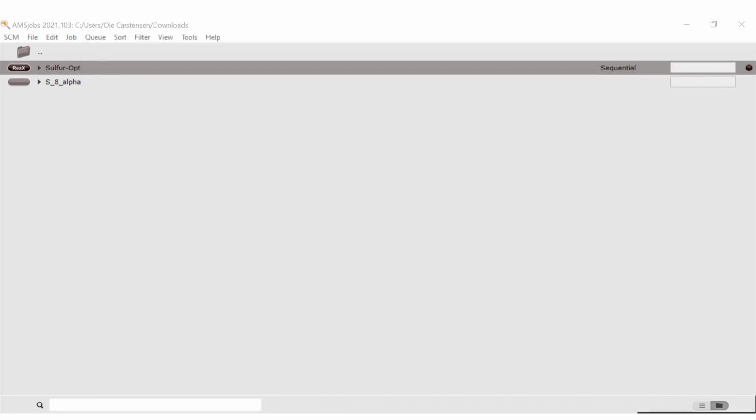In the next step, we are going to calculate the chemical potential of lithium that we need for the Grand-Canonical Monte Carlo calculation. And following the literature approach, we take the chemical potential of lithium to be the energy of one lithium atom inside a structure of body-centered cubic lithium, BCC lithium.